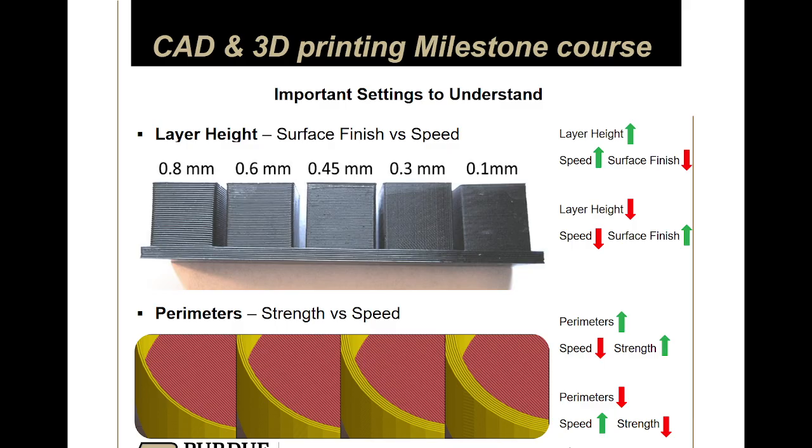If you think of your 2D printer, I don't know if you've messed with the settings before, but you can change the DPI on some printers to get higher or lower resolution. The layer height on a 3D printer is similar, but in the Z direction, or the vertical axis, right? You can change how precise your resolution is on the Z axis.